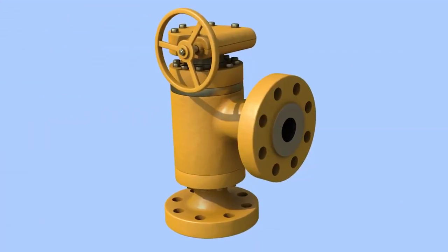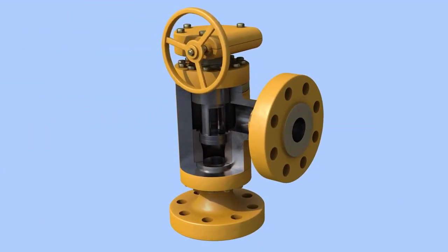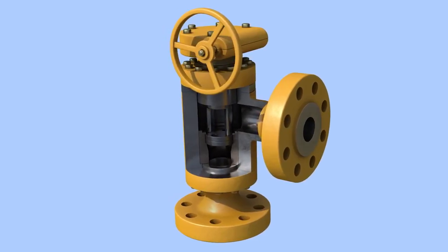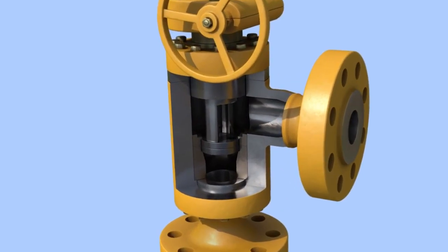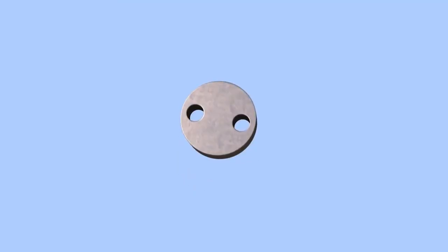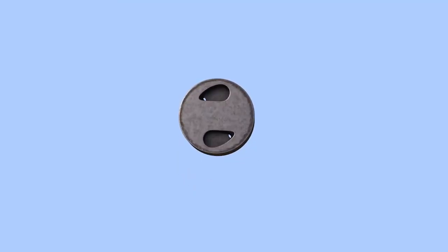Erosion is common around the edges of the holes. The high-velocity jets from the throttling ports flow into the valve outlet, resulting in high potential of valve body erosion. As the discs wear out, the valve's shutoff function could be lost.